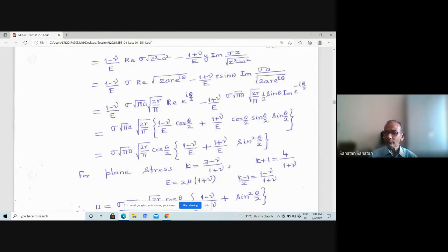And how do you find it? It gives you a biharmonic equation, grad 4 phi equal to 0. So one equation is given which involves only the function phi, the Airy stress function, and you can obtain the solution provided you select phi in such a way that it satisfies the boundary conditions. Then it is simply left to determine phi from that biharmonic equation. That's all. It actually makes life much easier and simpler to handle.